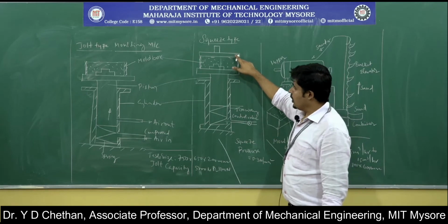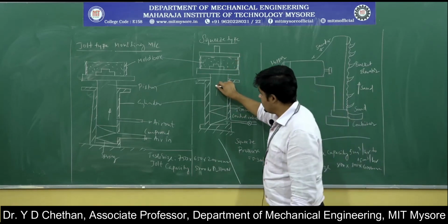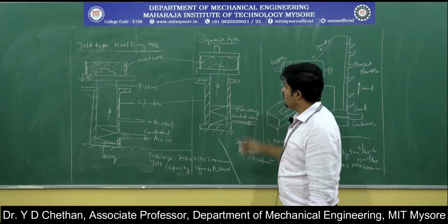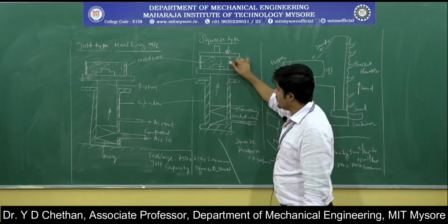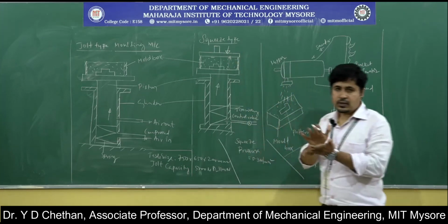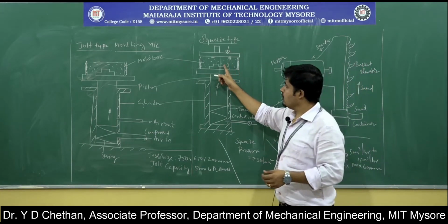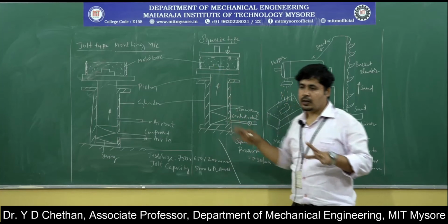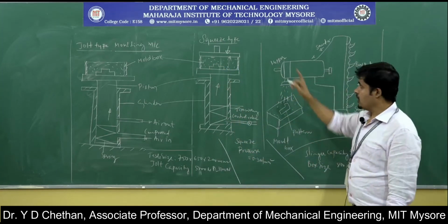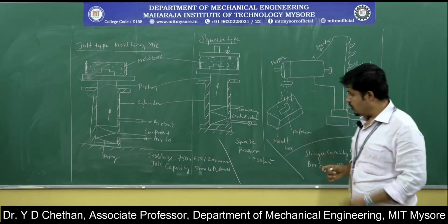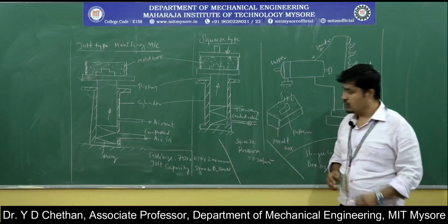Then the board compresses from the other end. So pressure is acting from downward as well as upward. That leads to the compression, or squeeze, of the sand and its ingredients. In turn this provides a perfect platform to have a good quality mold. That is about the squeeze type. If you talk about the specification, again the table size is 750 x 650 x 200 millimeters.